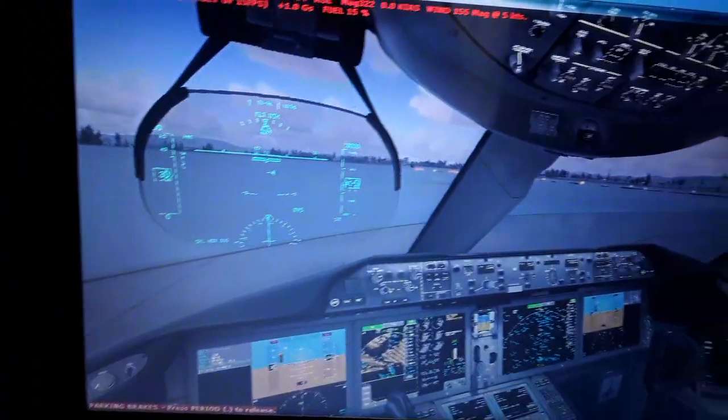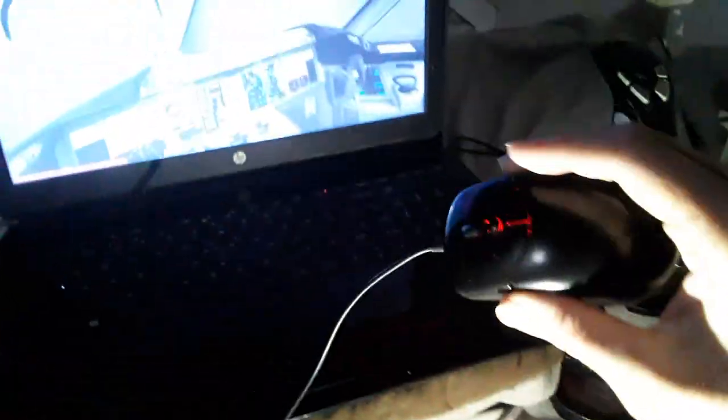The approach angle, we're gonna use the angle of approach. We're gonna use 25-30 degrees of flaps for approach and landing. 160, 170 nautical miles per hour airspeed, like 270 kilometers an hour. Pitch attitude of 9 degrees and landing gear extended, so you're gonna see the complete flight of the aircraft, also the flight line or flight path route. So I'm gonna start now using this mouse pad to create the flight line over here.